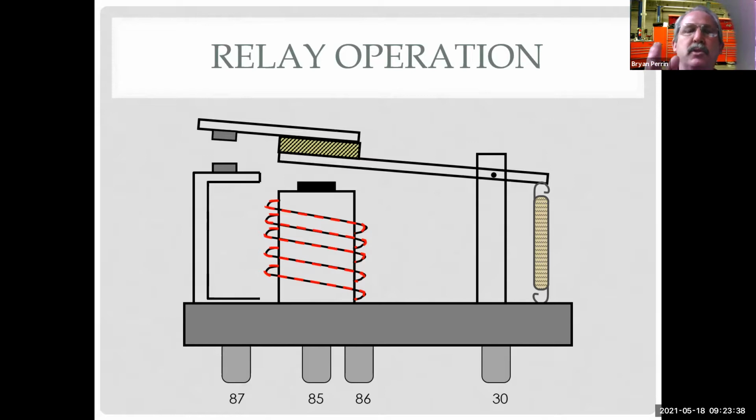A lot of times though, I need to control some of these things with an existing switch. For example, my driving lights, by law, can only come on with my high beams. So when I wired my driving lights, I took pin 86 and spliced it into the wire going to my high beam headlights.